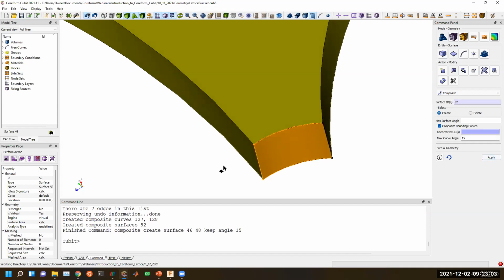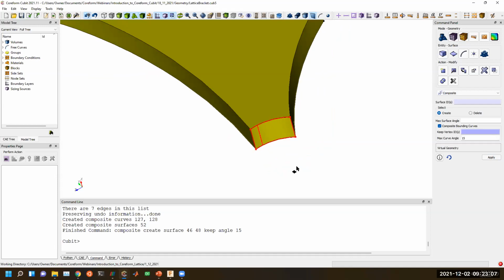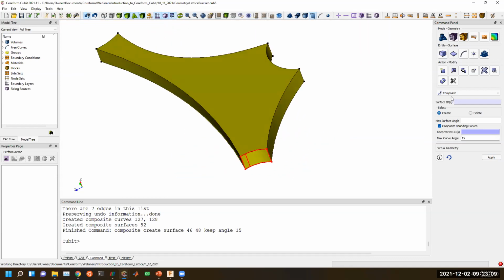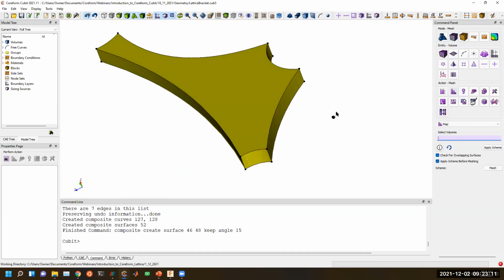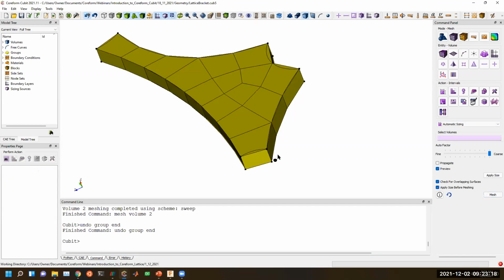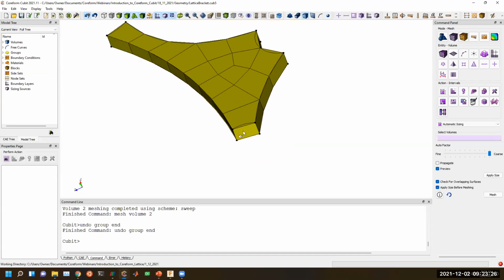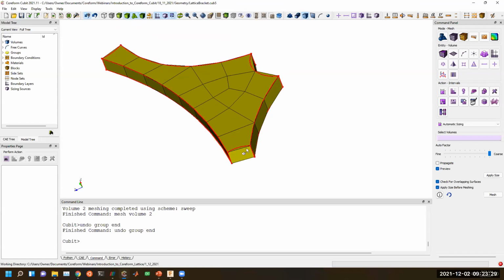And that will then remove the vertex or the vertices on the top and the bottom of this curve. And so now when we build this mesh, again very coarse just to demonstrate this, you can see that it doesn't require an element to conform to the surface that had been there. And so now we can get a very large element if we wanted to.